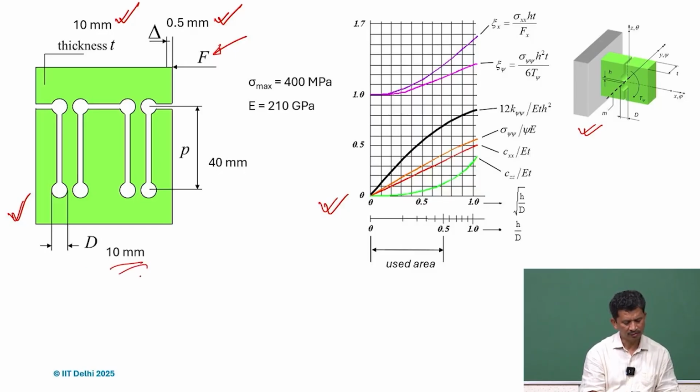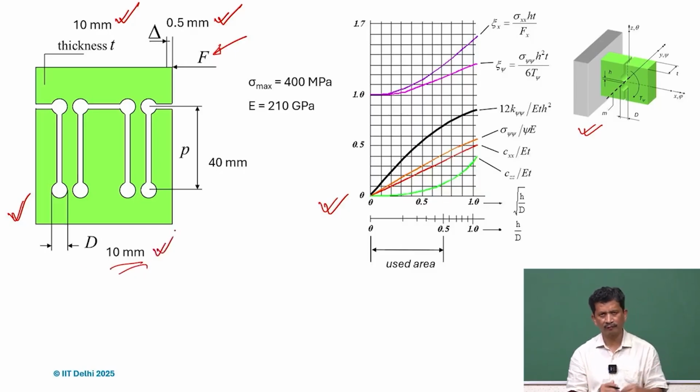The diameter, we can give or we can find. So some parameters we can assume, some we can find, because design is an iterative process. Some of the parameters in the beginning we may assume, and we can start. But suppose after calculation we find that it hits the manufacturing limitations, then maybe we have to rework and find different ways.